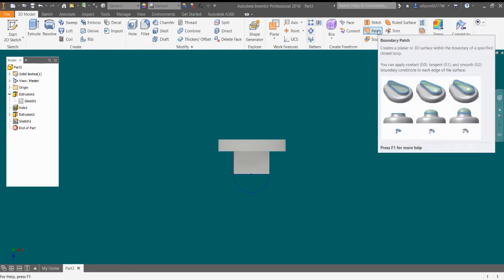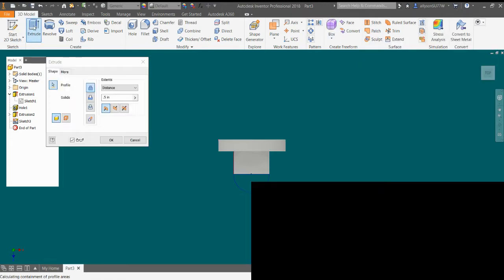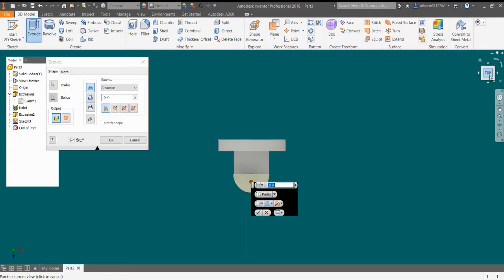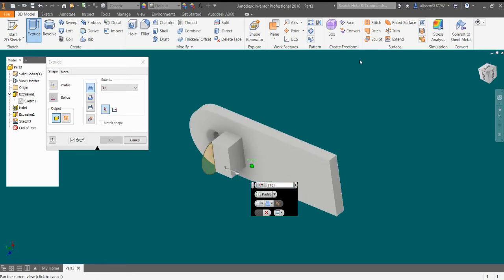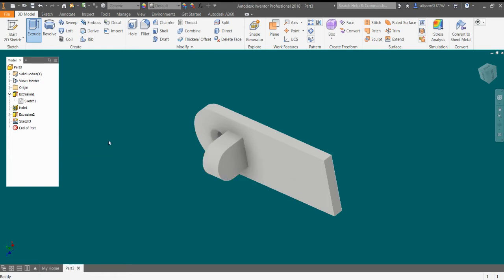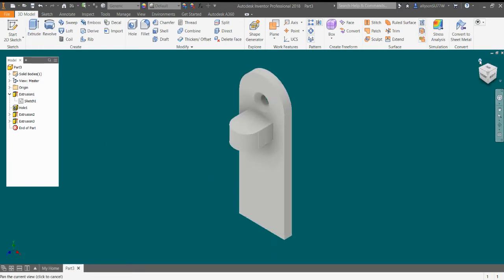And if I were to read, we need to make this tombstone, but we're going to extrude it. We're going to change that direction so it's going down. And we want to change that direction to 2. The reason we're going to change that is because if we ever change the depth of the rectangle, we want it to match. So there. Now we have our tombstone added to the rectangle that we just drew.